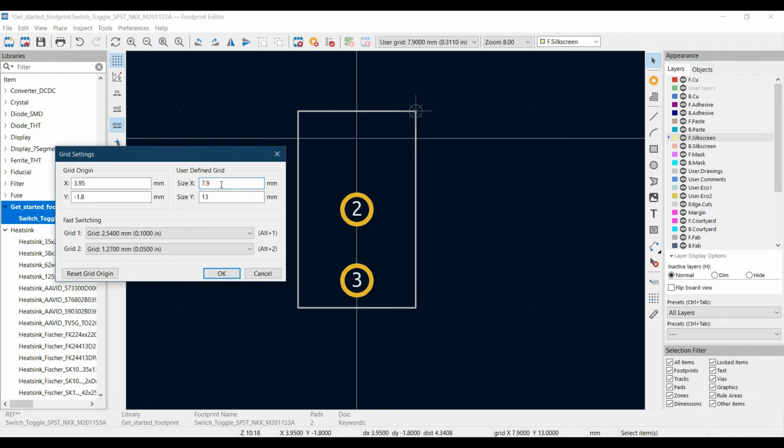So let's add over here plus 2 into 0.11, and similarly for Y we have to increase this grid snap to grid, this grid dot over here, slightly outward, equal to 0.11 mm distance.